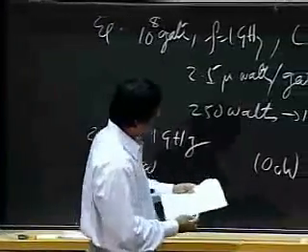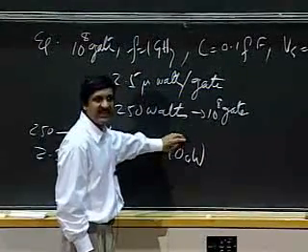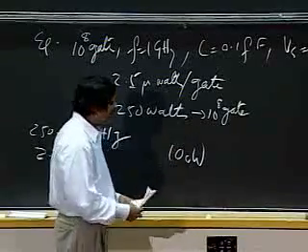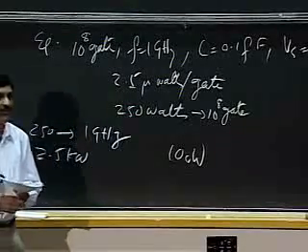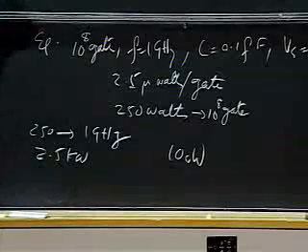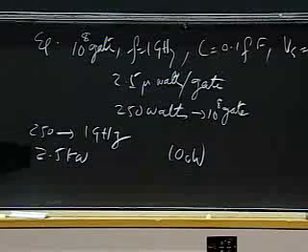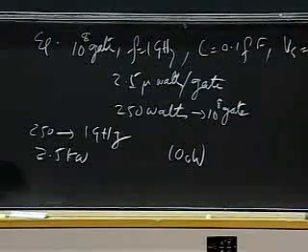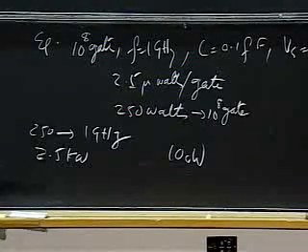But suffice it to say that the power discussion I've gone through with you is a very high-level discussion compared to the real thing. In real life, there is a fair amount of standby power even for CMOS logic. Although I don't have a path from Vs to ground for my 2 transistors, there are many leakage currents. Currents leak through all kinds of places, through the drain of your inverter and so on and so forth. And so there is some standby power.